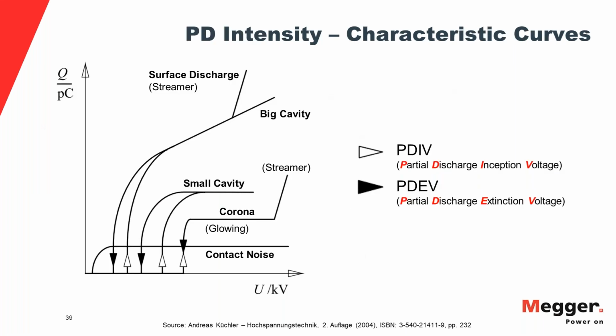And now just something about the intensity. What you want to see during PD testing, you're measuring various key parameters. And the most key parameter is the partial discharge inception voltage, PDIV, followed by the PD mapping, the intensity at U naught that comes out of IEC. The discrimination of the criticality should be done at operating voltage U naught. And then there's PD extinction voltage. You trigger an event. When does this event stop again? Or does it stop at all? That is kind of the relationship.